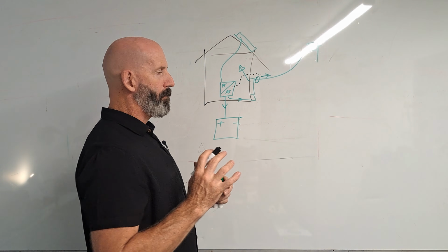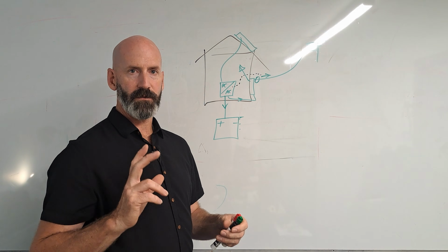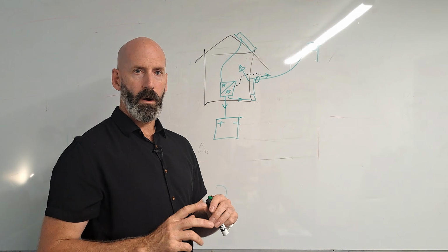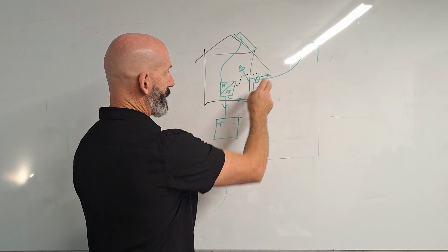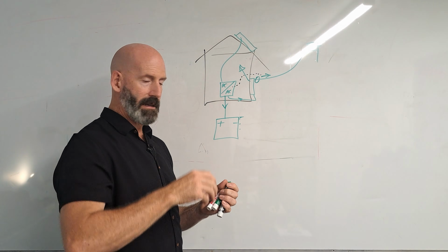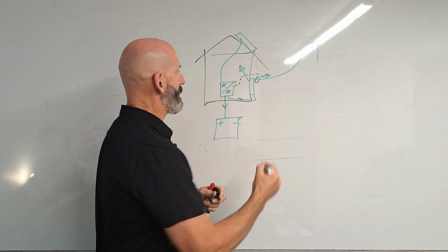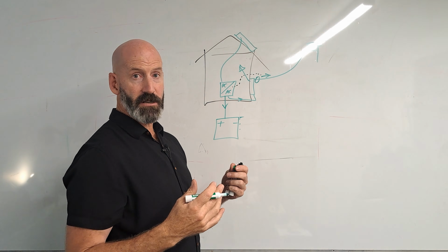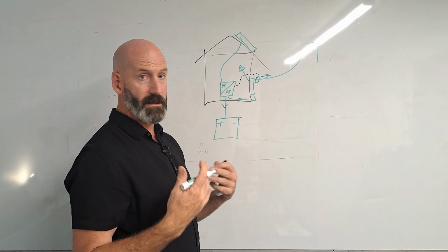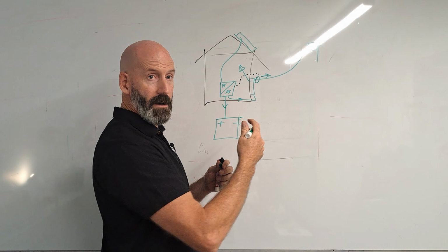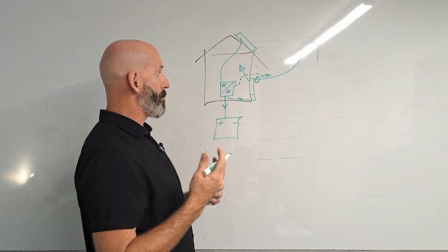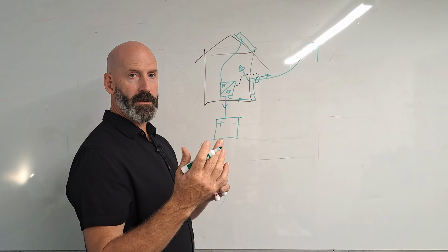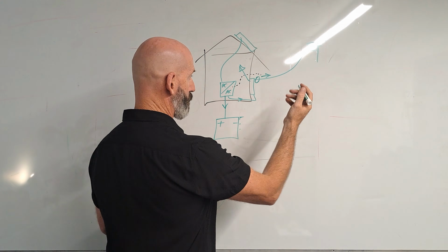So, most hybrid systems have a couple of conditions, and it's why they're hybrid and not off-grid. A hybrid system requires regular connection to mains power so that it can regulate and balance itself against an external source. It needs to see it pretty regularly. Most manufacturers, if you dig into it, are generally saying that it needs to be connected to the grid at least once a week. Otherwise, it will end up out of phase, like the frequency will fall out of parameters and the voltage can fall out. It kind of relies on the grid to find a reference point on a regular basis.